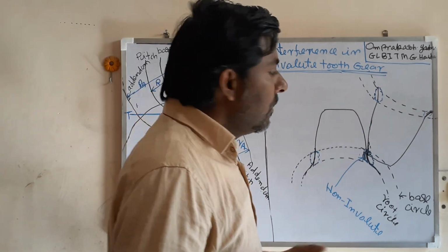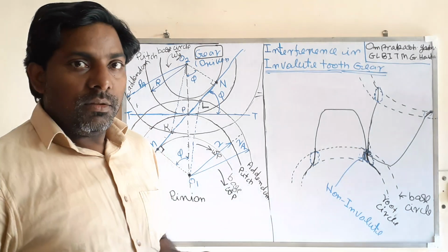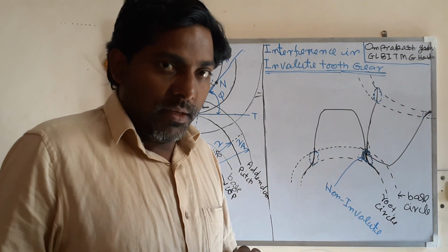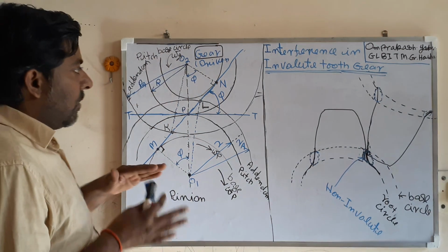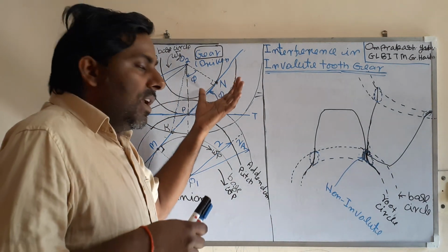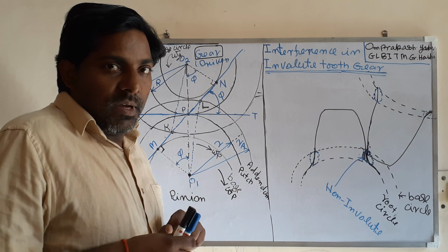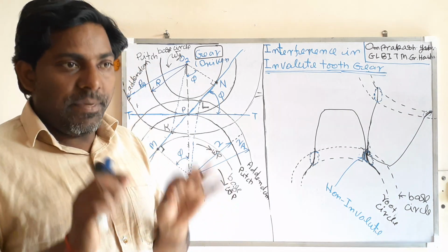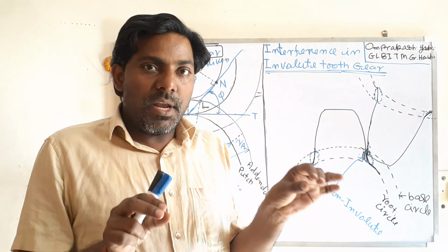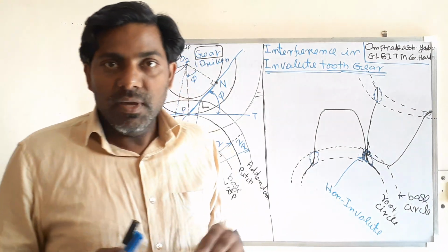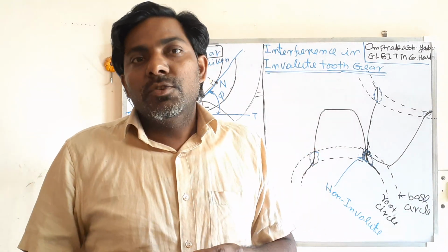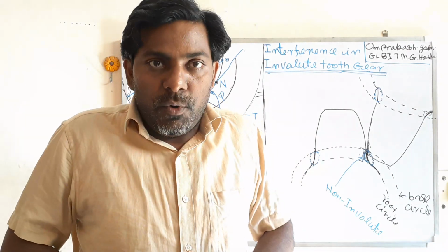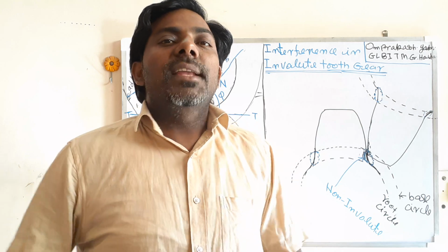Okay. Now, one thing I am going to show is a very interesting phenomenon. I have told you that either you increase the addendum of the gear or you increase the addendum of the pinion, but that is not the case. Because for the machine gear, the addendum of gear and pinion are the same. So you have to increase the addendum of both the gear and pinion simultaneously.